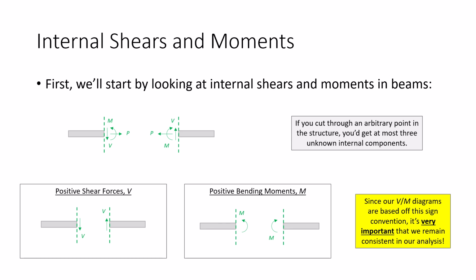The reason is that inside the table, right here, there are internal responses keeping the table upright. Analytically, we use the tool of cutting a section to investigate the internal responses inside that section. Some of this we've already dealt with. For example, if there's an internal axial load P, we can divide it by the area to get an internal axial stress. Then we can compare that axial stress against sigma allowable, factors of safety, etc., to see whether the member is too stressed.